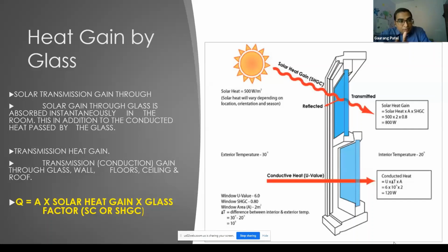So that convection comes first, which is a combination of your hot air plus the movement of the air, and that transfers the heat from outside to your wall first. Then conduction happens, and then inside the room you have low air movement and that hot wall, and that air movement inside the room takes the heat from the wall and transfers it into your room.